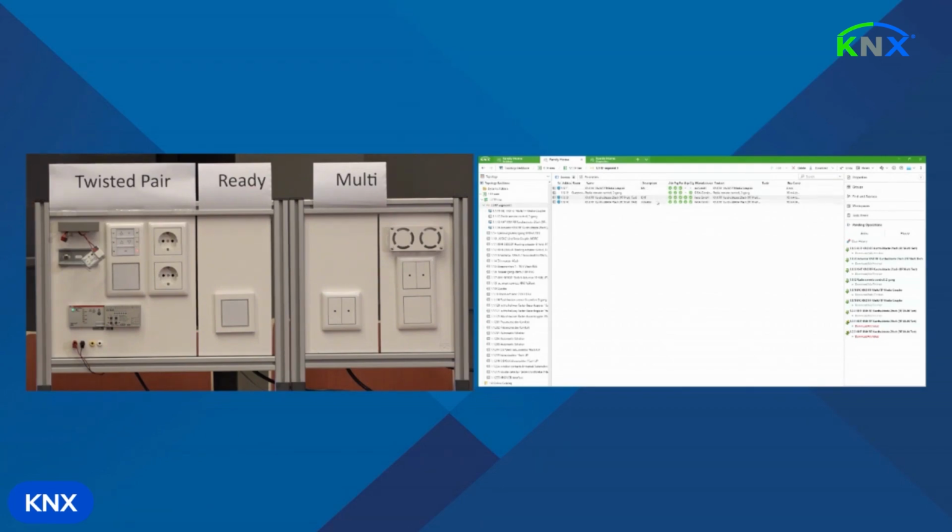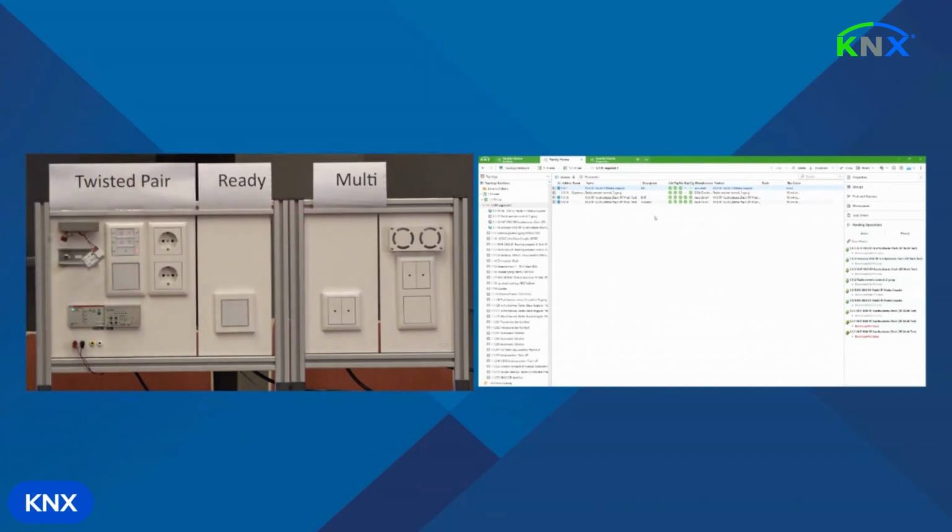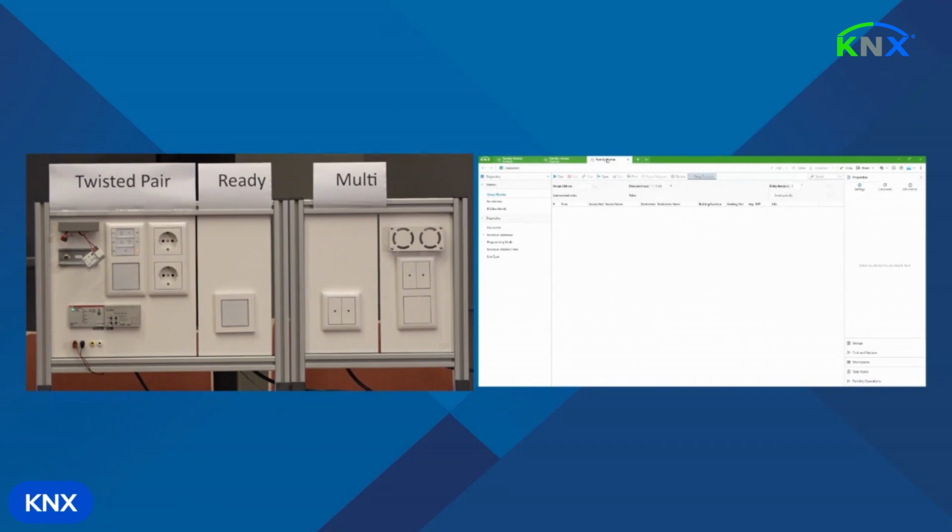Indeed. So now I programmed the push button and the actuator. I will also program the media coupler. Or should I not do that yet? Not necessary in this step. We only did the connection between the two radio frequency devices. Okay. But if you go to diagnostics now. And I don't have to do that yet because they communicate directly. Yes.